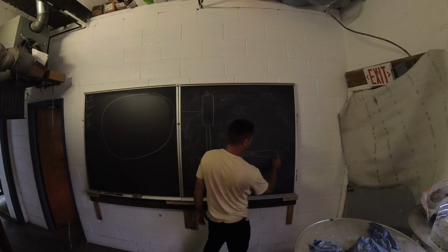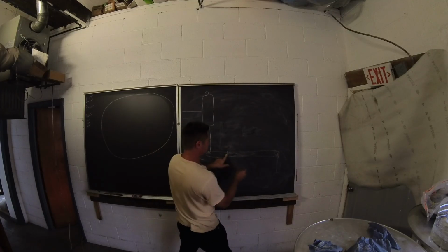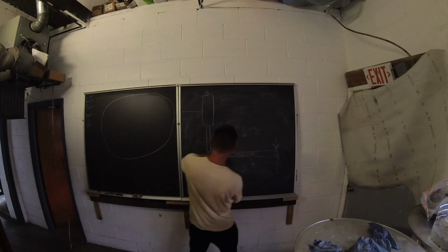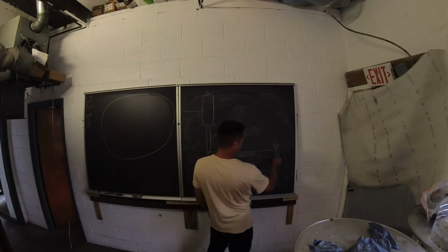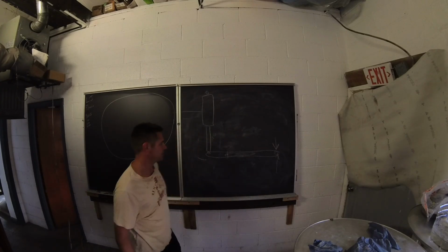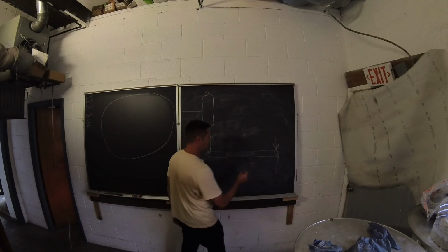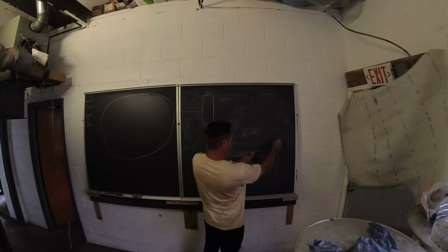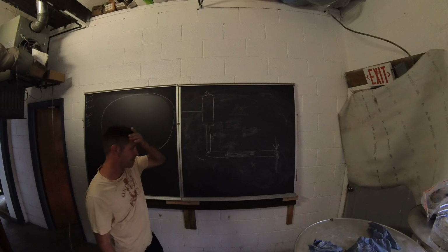You have mechanical advantage in the lever arm, so if you lock the pivot here and push down, we'll say it's 4-to-1. So if it takes 10 pounds of force to move this an inch, well, 2.5 pounds. Now you move that pivot, you can put a gear rack or something, a servo motor. But regardless, you can make a system where moving this eyelet up or down is anywhere from 2.5 pounds consistent to 10 pounds, or maybe 20 pounds.